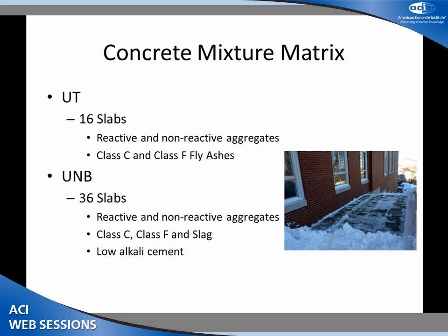So at the University of Texas, we cast 16 slabs. We looked at reactive aggregates and also non-reactive aggregates. And again, we looked at Class C and Class F fly ash. And we made half the slabs, and then the second half of the slabs. So we had one set that was just the control, and the exact same slab, the same mix, we actually sprayed with potassium acetate.